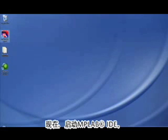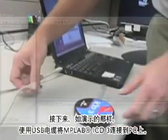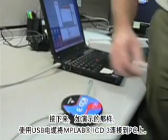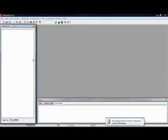Now, start MPLAB IDE. Next, connect MPLAB ICD3 to the computer using the USB cable as shown. At this point, Windows will automatically install the drivers for MPLAB ICD3.